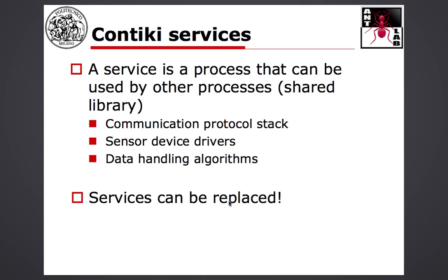And this is exactly what I was saying. Okay, so a service is a process that can be used by other processes, and to some extent it's some sort of shared library. Okay, that you load and other processes can use. Examples are the communication protocol stack, or the drivers for communicating with the sensors, or maybe algorithms for handling data.